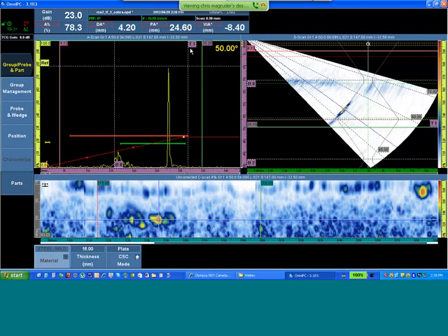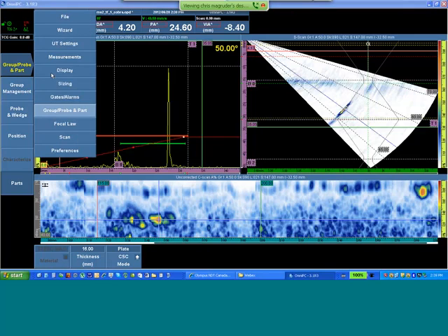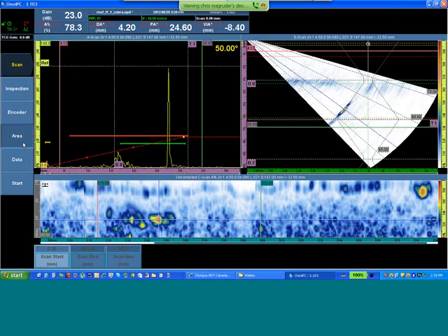So it would continue B2, T2, T3, B4, so on and so forth. Looking at our C-scan that we see here, we performed an inspection from 0 to 300 millimeters at a 0.5 millimeter resolution. The scan started at 0 and stopped at 300, and every half millimeter we have a slice of the weld